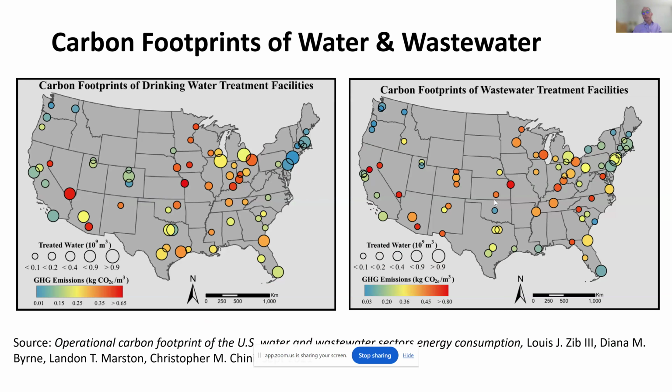I talk also about water and wastewater, so the B7 emissions module. And ASHRAE Standard 240P also addresses this. It is an overlay of a couple different things. How your region and your municipality gets water. Is it surface water that you can just drain by gravity? Or is it groundwater that you have to pump out? Is it water that you're reclaiming from the sea in a desalination plant?